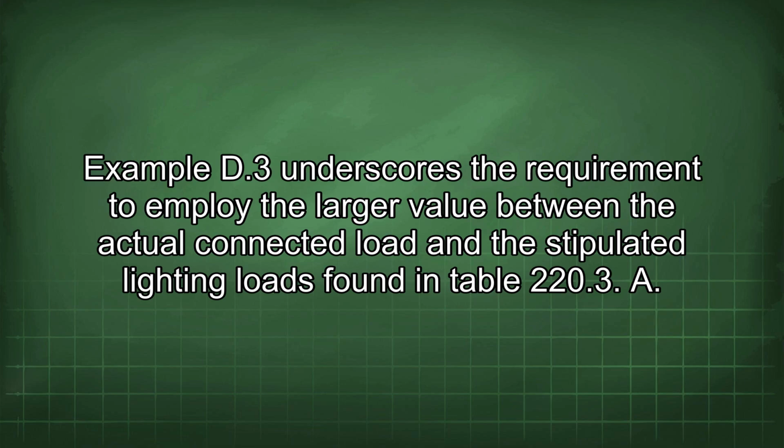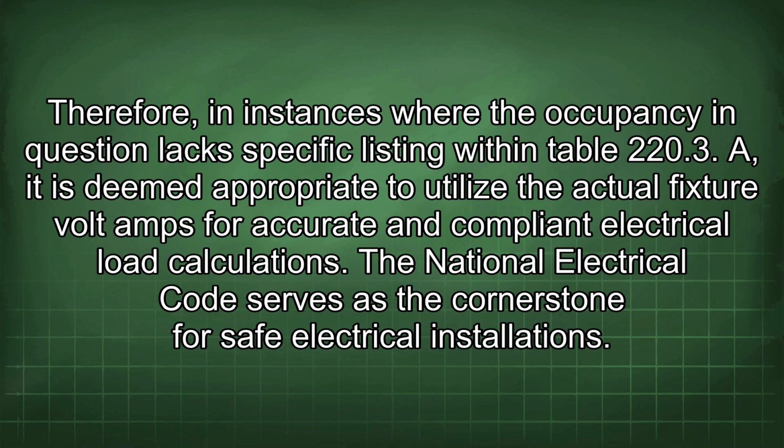found in Table 220.3. Therefore, in instances where the occupancy in question lacks specific listing within Table 220.3, it is deemed appropriate to utilize the actual fixture volt amps for accurate and compliant electrical load calculations.